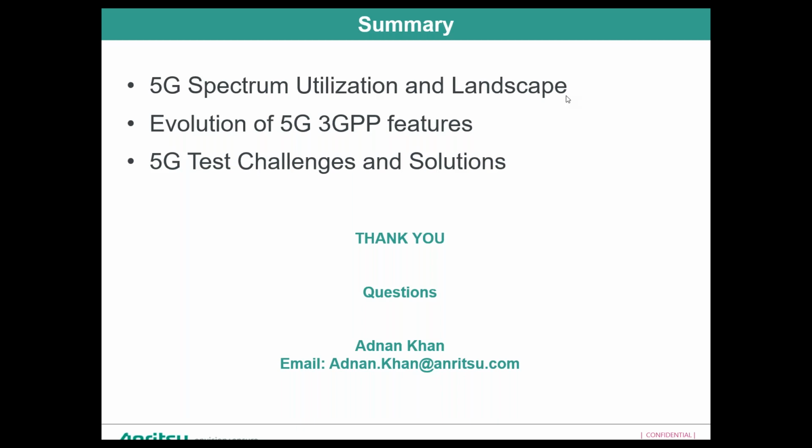You want to make sure we're getting the right quiet zone, and that the amplitude and phase are within a certain amount of measurement uncertainty in that specific quiet zone. So again, it's done on a yearly basis. Characterization happens once, and after that you have what we call the calibration, again on an annual basis.